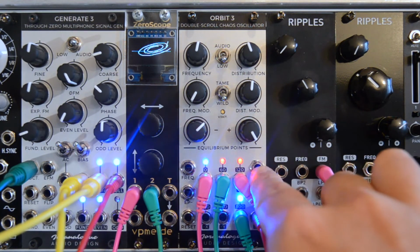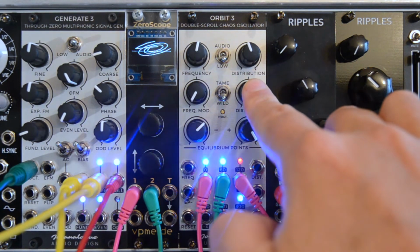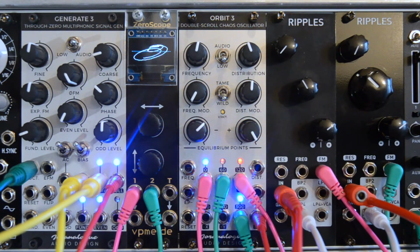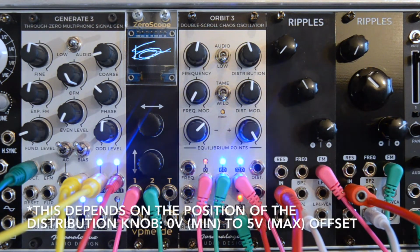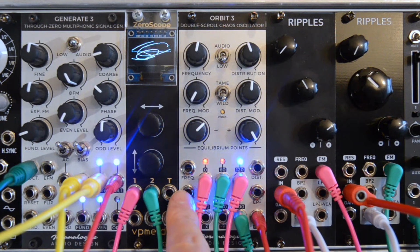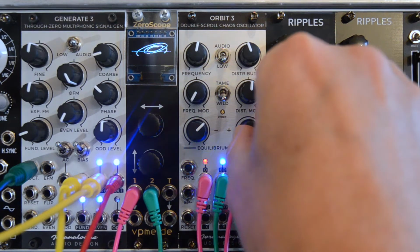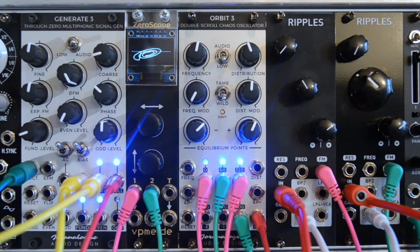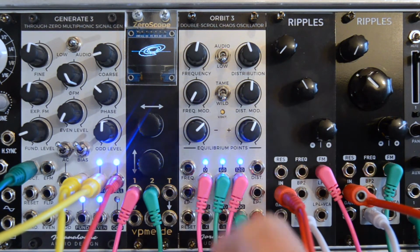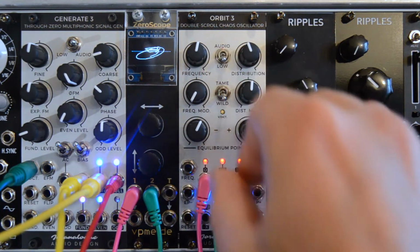The distribution modulation input accepts bipolar signals as well. The according knob is a polarizer too, so you can invert and attenuate the signal. Maximum modulation is achieved with -5 to +5 volts. The inputs for the equilibrium points accept bipolar signals too, but the knobs don't turn into polarizers. Instead, the signal at the inputs is just added to or subtracted from the position of the knobs.